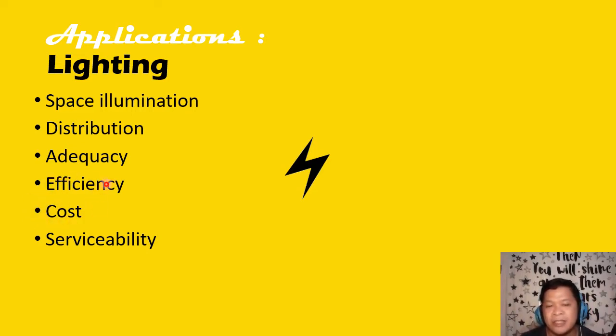If you get more efficient lighting or just the right amount. Then there's also the concept of serviceability, because when you have malfunctioning lighting in your production area, that could cause probably errors not just for the humans but also for the sensors that may be dependent, for example, on lighting requirements. Like, say, if it's an optical based sensor, okay? So we need something that's easy to replace, etc., or repair.